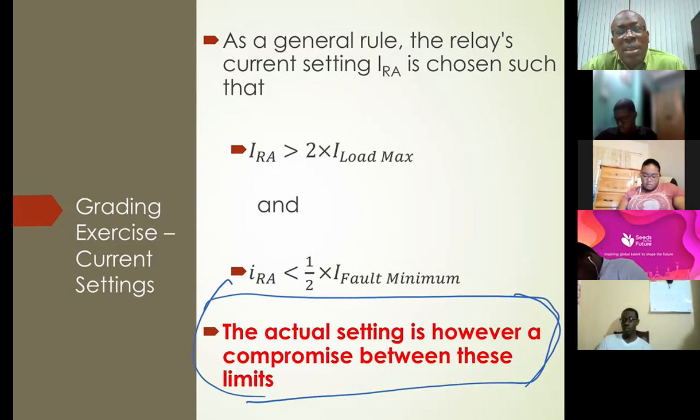So although I give it as the rule, what you want to ensure is that the load current will not result in the relay operating.